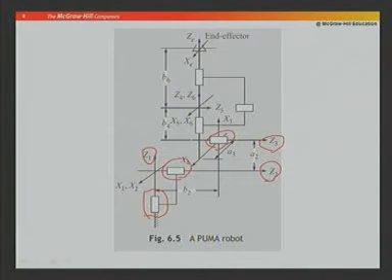With it, I am now connecting my wrist joint, which is my Z4, and Z4 is here, and then I have a perpendicular to it Z5 which is here, and then this is my Z6 as per the symbol we have adopted, and this is my X6, and notice all of them are intersecting at this point. So, the way we have analyzed the spherical wrist, all the coordinate frames of last 3 joints' origins are taken at that big red dot point.